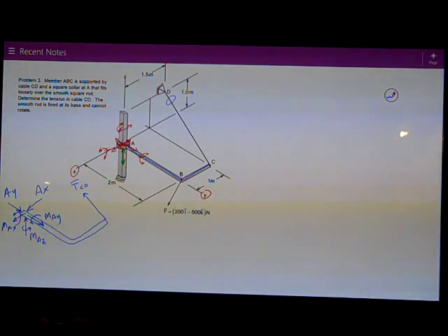So we'll talk more about these forces as we sum them all up and write them all out. And then finally I have the applied force, which is this F, this 200i and negative 500k. So I would probably write it as F equals, I don't want to miss that 0 in the j position, so I'd write it as F = 200i + 0j - 500k newtons.